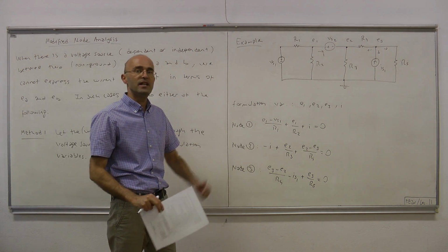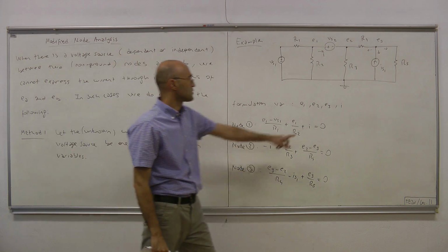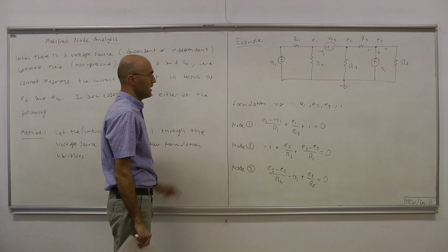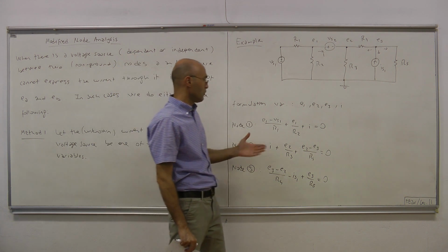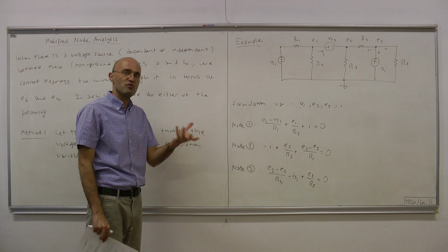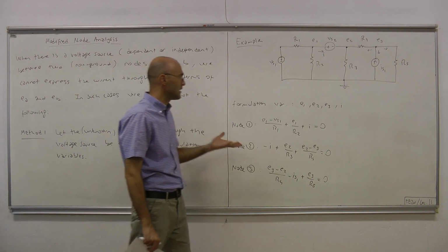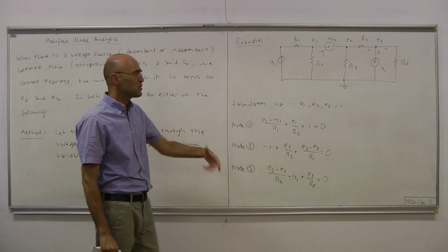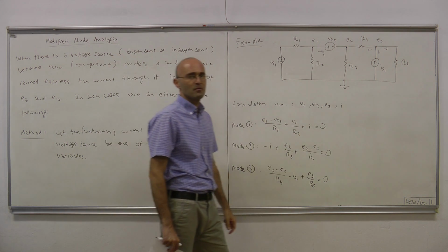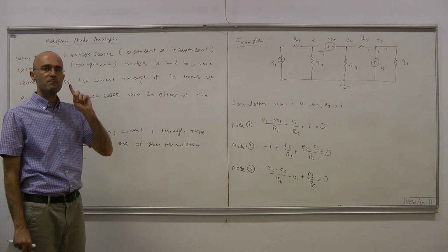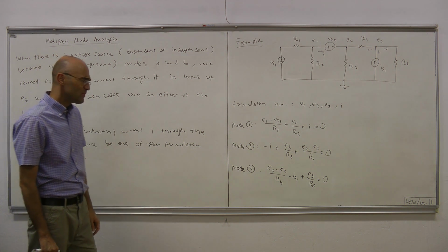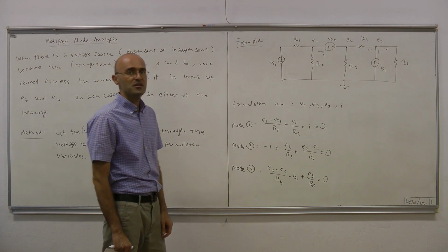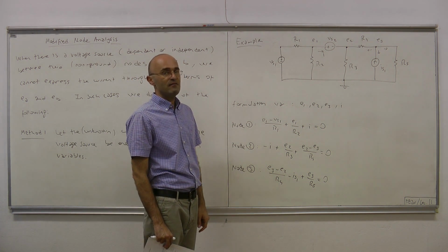So everything is nice. Without any problem, we have been able to write down the currents, because we don't try to express this I in terms of node voltages. Now, here there's a problem. All these equations are, in terms of our formulation variables, legitimate, but the number is 3. We have 3 equations. However, we have 4 unknowns. That means we require 1 further equation. And that equation will not be coming from KCL. In this case, it will be coming from KVL.